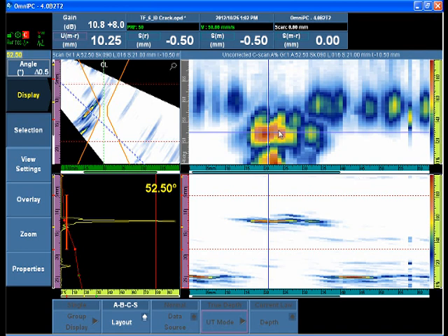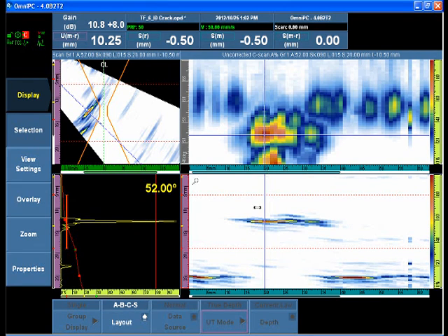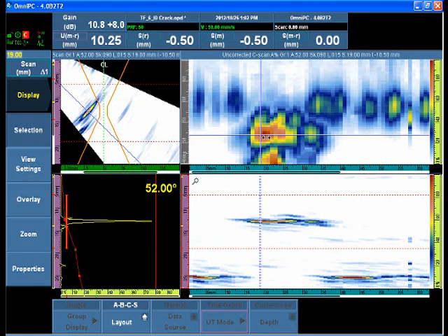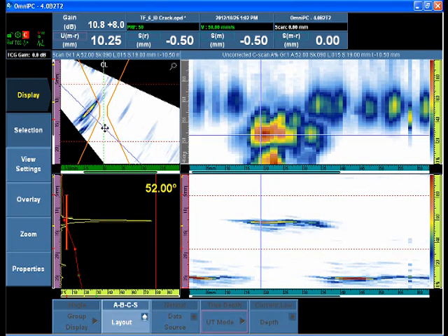The C-scan, uncorrected amplitude-based C-scan, is the result of the gate. Every A-scan in the sector scan, for every millimeter of travel by the scanner or probe, generates the pixel for the C-scan. The advantage of the B-scan is that I can see both the depth, height, and length of a flaw in one 2D display. The disadvantage is I can only project that for one focal law at a time.